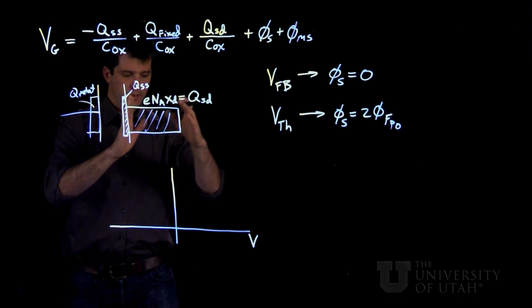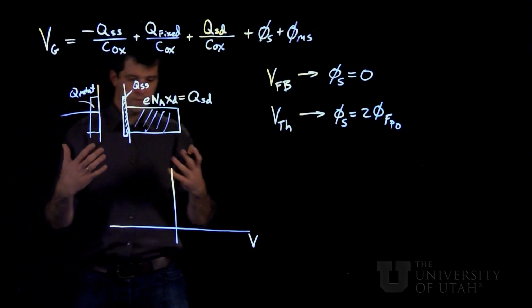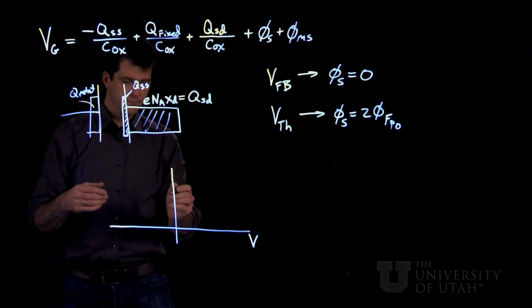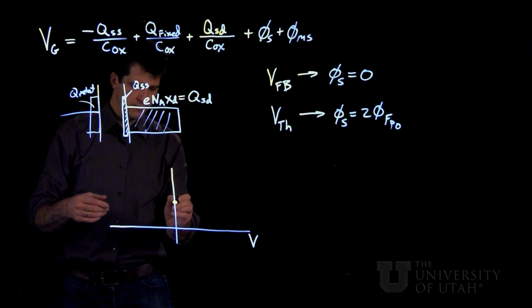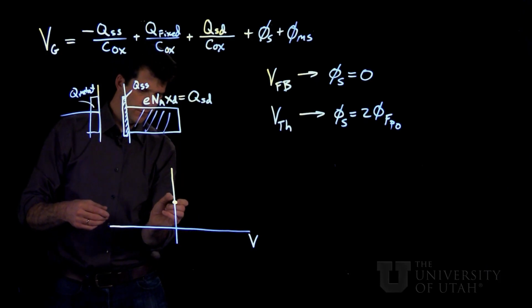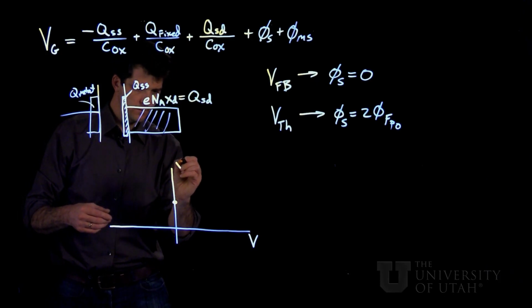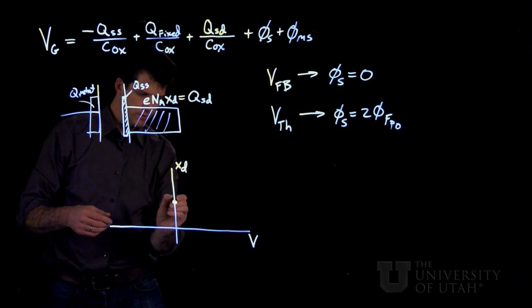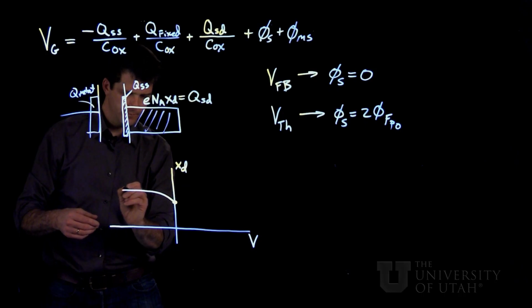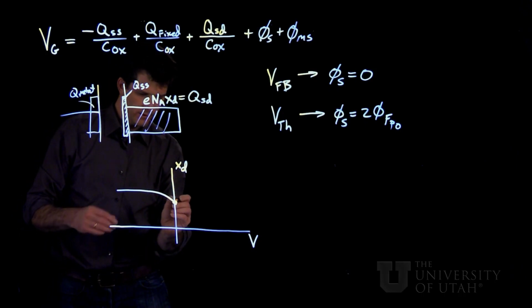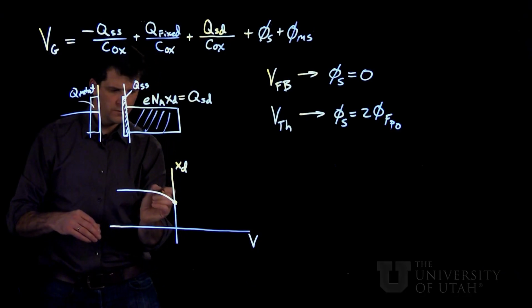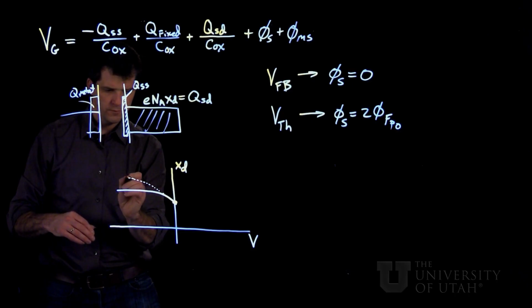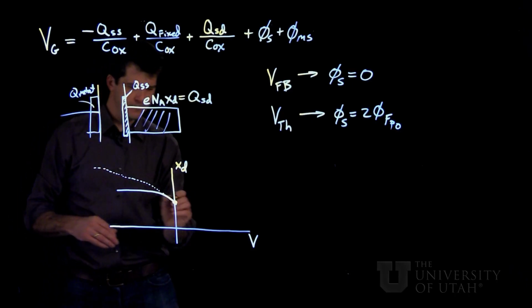Now, the interesting thing that happens is this means we're going into reverse bias. At zero applied voltage, we've got some depletion width. But what happens is that depletion width saturates as a function of reverse bias instead of continuing to move as the square root of applied voltage.